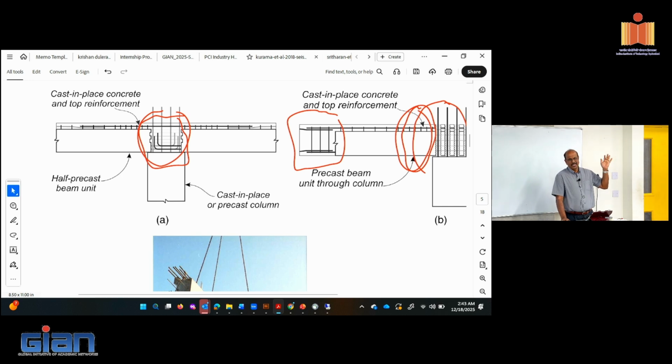So in the late 80s onwards, what the committees or the courts allowed is that you could use precast, but only for parking structures or less critical structures. Warehouses they allowed, parking structures they allowed. But the earthquake itself in 1994 showed that a lot of the parking structures actually failed quite a bit. So the committee members who were opposed to the idea of promoting precast members basically said, we told you so, right? So their concerns became more serious at that point.